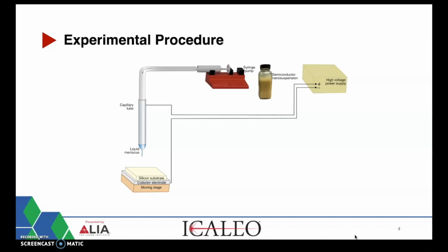Additionally, an electrostatic field is created by applying 3000 volts between the needle and the substrate, which work as electrodes. Subsequently, microdroplets ranging from 70 to 80 microns are generated using this electrospray. Eventually, these droplets interact with the laser.